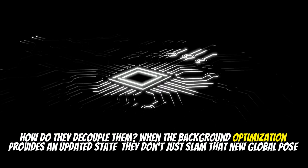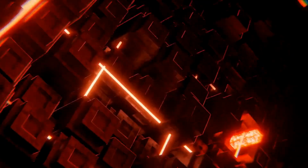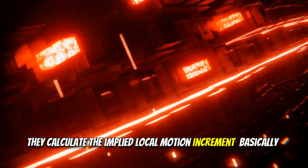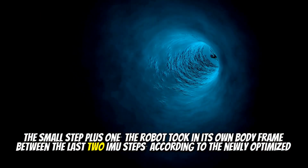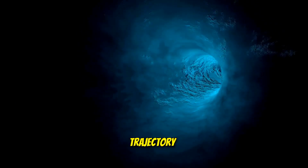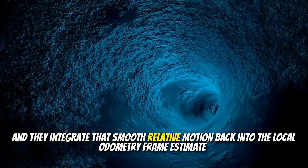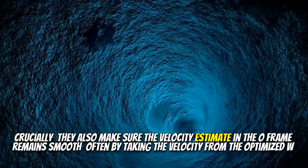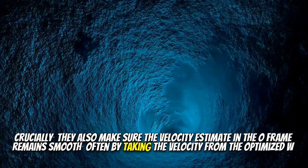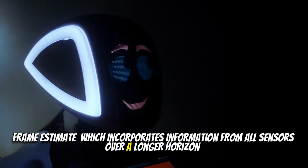When the background optimization provides an updated state, they don't just slam that new global pose into the O-frame. Instead, they look at the change the optimization made. They calculate the implied local motion increment, basically the small step the robot took in its own body frame between the last two IMU steps, according to the newly optimized trajectory. So they extract the smooth, corrected relative motion. Yes, and they integrate that smooth relative motion back into the local odometry frame estimate. Crucially, they also make sure the velocity estimate in the O frame remains smooth, often by taking the velocity from the optimized W frame estimate, which incorporates information from all sensors over a longer horizon.